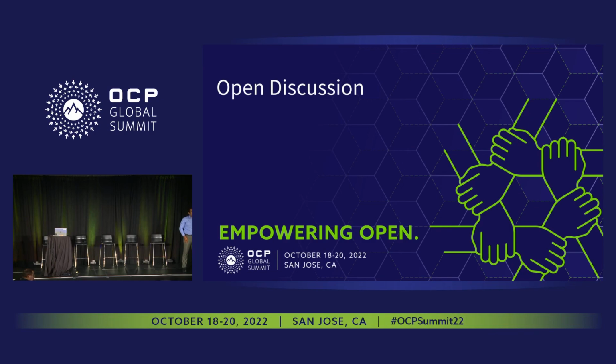Very unbiased opinion. You mentioned the categories of TCXOs and OCXOs based on certain parameters like DFE, which translates to the frequency slope and temperature. I agree with you, that is very important, and especially during a long averaging time, the frequency slope is going to have a big impact. But I request the forum here to adopt not technology-specific names, because as you mentioned earlier, there are certain technologies that don't need to follow the traditional XO approach. We should just call it a classifier which talks to these parameters, rather than saying that you need a TCXO or an OCXO to meet certain requirements.